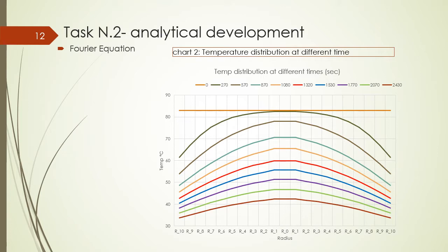So here are displayed the temperatures inside of the potato, but for different times, starting from the upper part up to the lower, the time is increasing. What is interesting to notice, at the very beginning the temperature is always the same, but also at the very end, the temperature is approaching to be the same, and the changes are happening only in between.